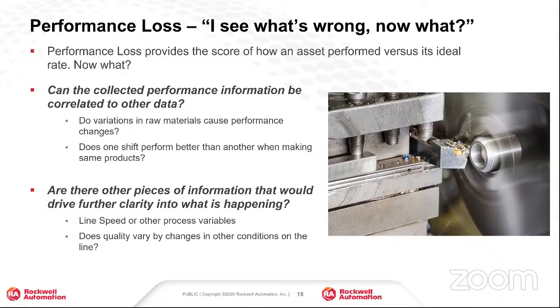So then quality, the third aspect, is a little bit difficult, but it can still be measured. Now it's a ratio of good material to all material. In the process of manufacturing, all the continuous process output is measured for quality through LIMS, the laboratory, and also through analyzers, the process analyzers. And that specific quality measurement is used to calculate the quality aspect of the OEE.